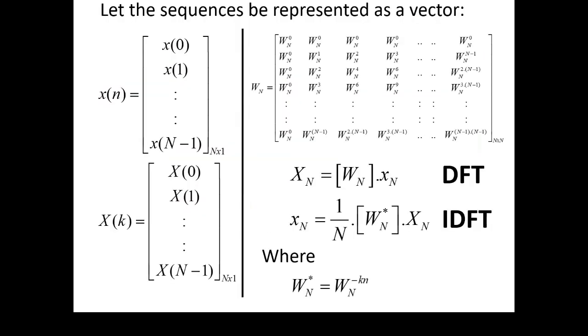Now, how to calculate the Twiddle factor for any given N? So what you have is n and k, so you have 0 1 2 3 and so on, then you have 0 1 2 3 and so on, up to N, here also you have N. Okay, so for W_N, what would be nk? 0 0.